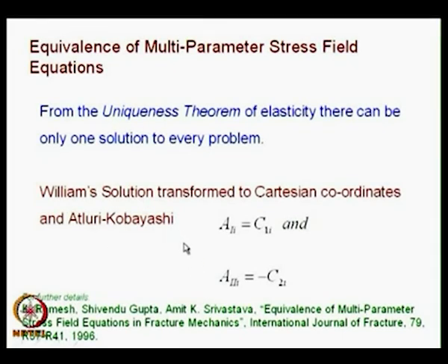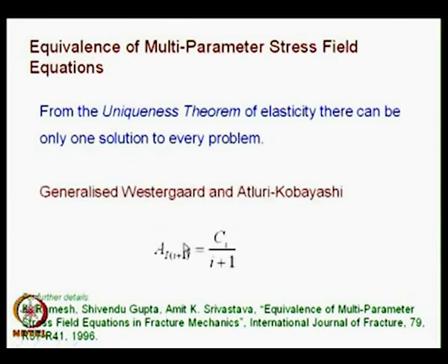You can do a similar exercise for the Westergaard solution also, and in the class we have developed it for the mode 1 situation, and the interrelationship is the coefficient a_I of I plus 1 equals C_I divided by I plus 1. For the case of mode 2 loading, I have given you the Airy stress function.